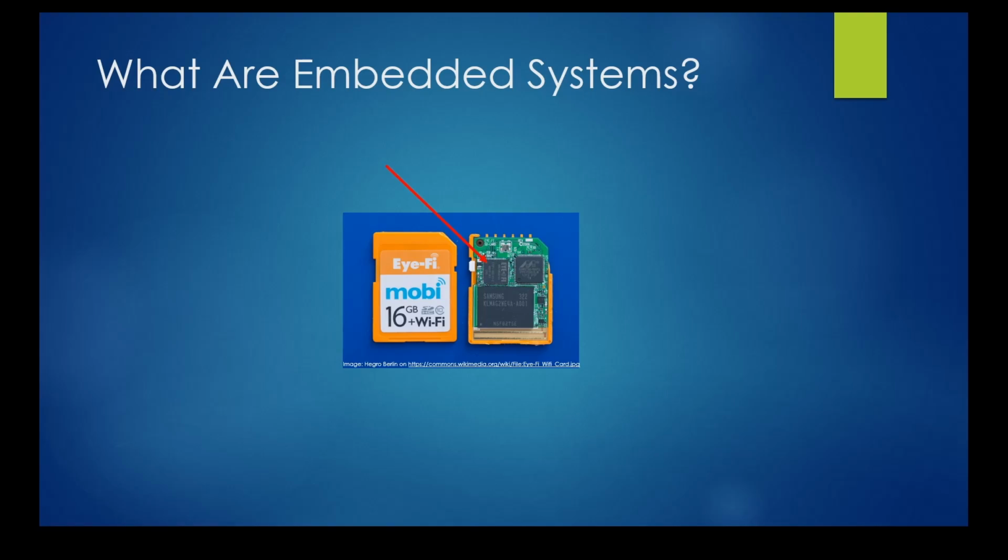It can be looked at as a small computer capable of running embedded software, also called firmware. Firm, because it cannot be arbitrarily replaced by a user, although it can sometimes be updated, as we will discuss later. This chip is a WLAN SoC, or System on Chip, by Marvell. It also contains a microcontroller, a CPU, and is a tiny system in its own right. This chip is a Samsung eMMC device, a storage device. It too has, you guessed it, a CPU on board that runs firmware.